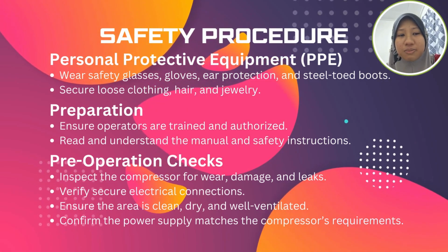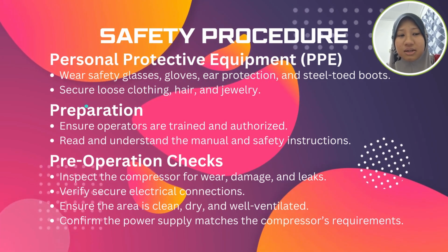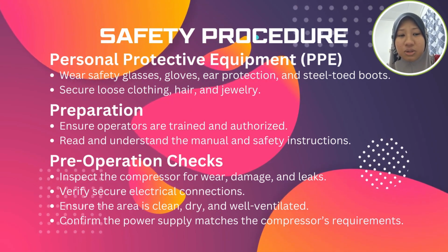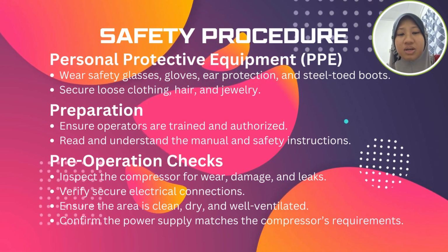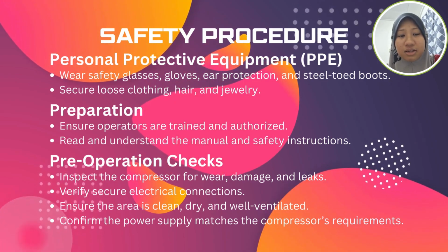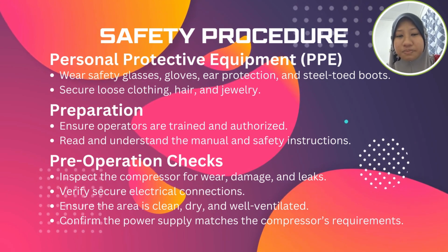First, personal protective equipment (PPE): wear safety glasses, gloves, ear protection, and steel boots. Secure loose clothing, hair, and jewelry. Second, preparation. Ensure operators are trained and authorized. Read and understand the manual and safety instructions.